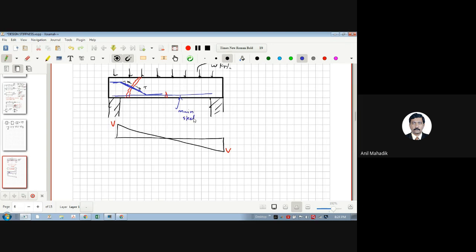So it is helping to arrest this crack also indirectly. And that's why you might have seen that whenever we calculate the shear capacity, we also check the main steel percentage, PT. We calculate the PT, and as this PT is more, the capacity will be more for the shear reinforcement. Here I can put the main reinforcement, which we generally call bent up bars. Nowadays we are not providing these bent up bars practically unless there is an exceptional reason. It is not general practice.